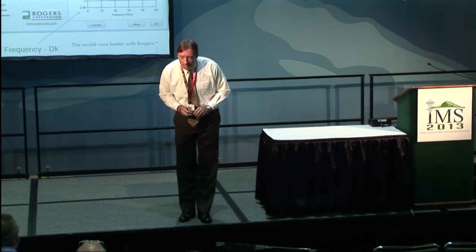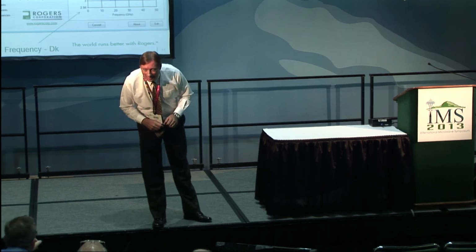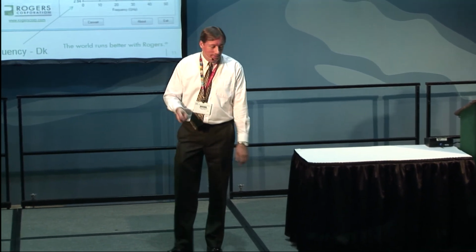Yes, sir. I'm sorry, I couldn't hear you. Oh, yeah, that's another good question too. The question was if we're going to be putting these curves on our data sheets. On the RO4000 data sheet, I believe we already have some of these curves, and we're talking about adding that to more of our data sheets. And there's pros and cons to all that, of course. The good side of that is you can look at a specific frequency and see what the dielectric constant is, but that's also for a microstrip transmission line only, and if somebody's designing a strip line or a coplanar, there could be some subtle differences. But this is really meant to be a good approximation of how the circuit's behaving. But yeah, we've already got that on our 4000 data sheets, if I'm not mistaken.